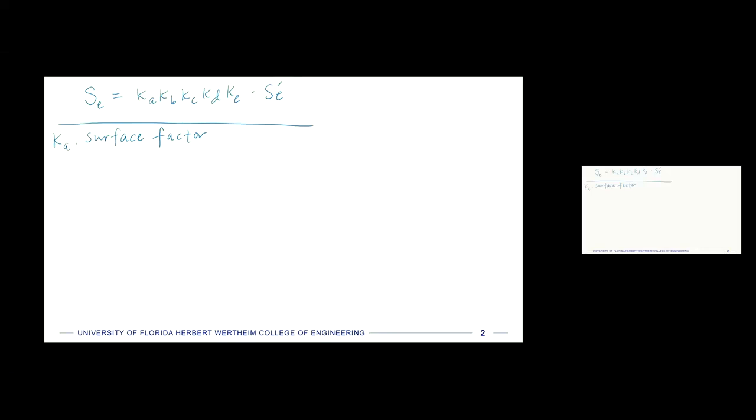They give us a lower stress that we have to stay underneath on our component to have an infinite life. You can apply these also to other fatigue strengths that are not at the endurance limit, and it's just going to decrease whatever the fatigue strength is at the number of cycles you're trying to aim for. It just drops it down. So for the surface factor, I'm going to put a plot here, and the y-axis is going to be that surface factor. And this one is, I think, the one with the broadest range, so actually going to go from 0 up to 1.0, the whole range.